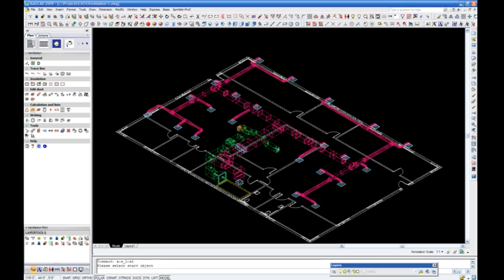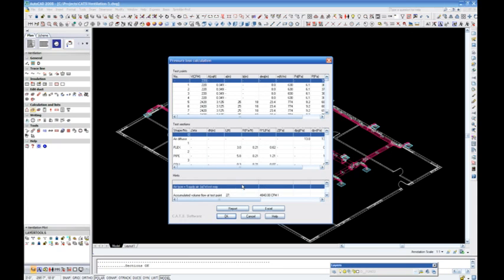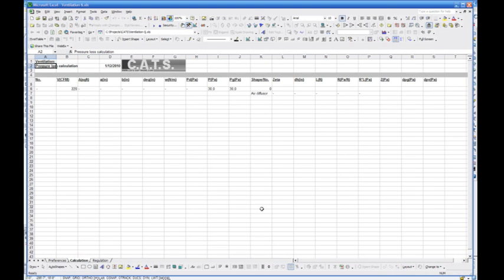Here again we have our total CFM and pressure drop of the entire supply duct system. All information can now be transferred to an Excel report. Each fitting in the supply duct system is listed with its associated pressure drop. Each diffuser is listed with respective pressure drop.